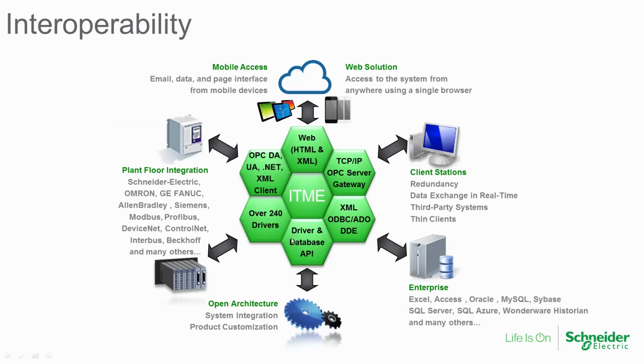Now, this interoperability diagram here, if you think of InTouch Machine Edition tags as the core of this, and being able to communicate to not only Schneider PLCs, but Omron, GE, Allen Bradley, you name it, that's kind of the main idea, to communicate to PLCs and these other devices. But if we don't have a driver, you can also communicate via OPC.